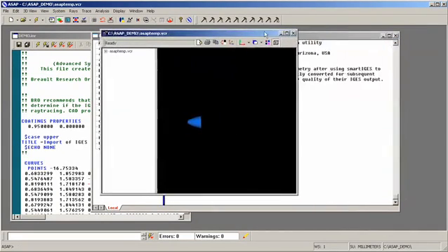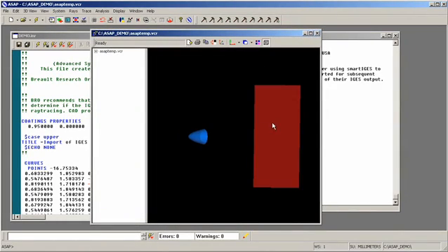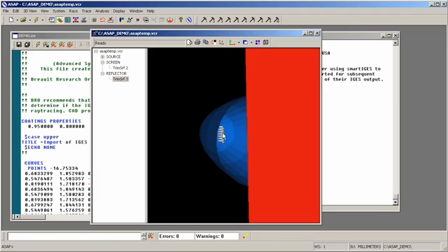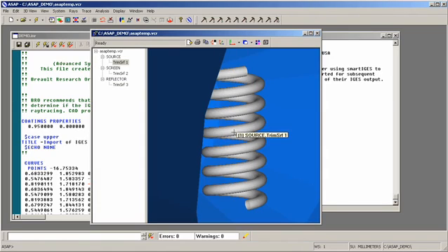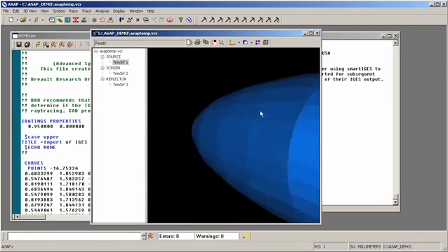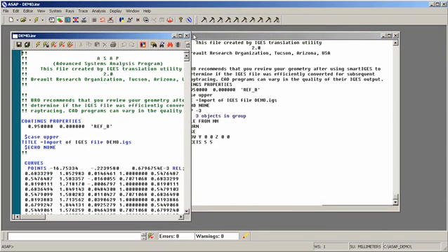This is the ASAP 3D viewer window. There's the screen, here's the reflector, and if I rotate this about, there's the filament. Now if you look closely here, you can see that the reflector looks faceted. That's just a result of the graphical resolution. This has no effect on the actual simulation result. During the ray trace, ASAP will use the curved surface. So the geometry looks okay.